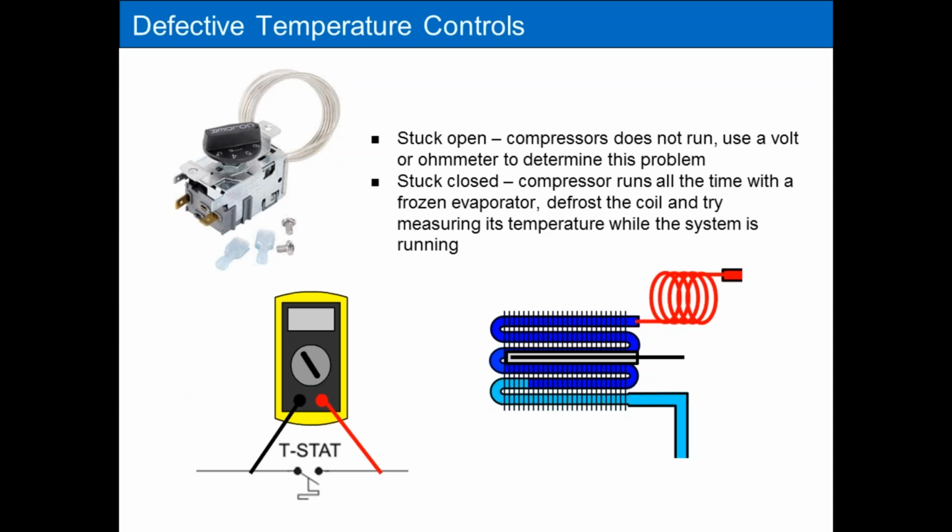If you never get down to that setting, let's say 20 degrees, and your coil never gets down to that setting, well, that's a problem. That's why the unit's never shutting off, because the coil is not getting to the right temperature for another reason. So you can segment whether it's the temperature sensor or another system problem that's causing it to run too long.